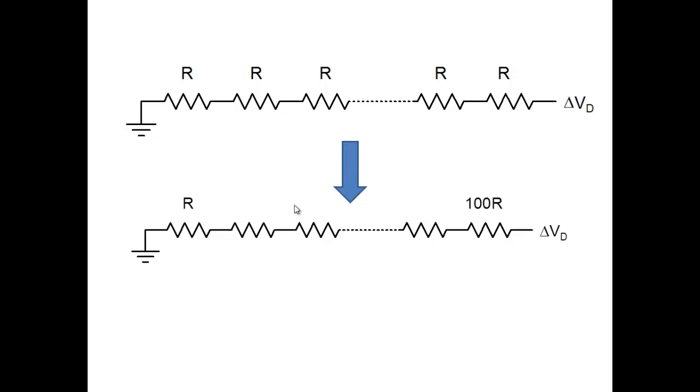At this end, remember, the resistance is still R, because near the source nothing changes. So this element is R. And at the pinch-off point I've arbitrarily put 100 R. You can put 1000 R depending on how large the resistance became. Correct? Because there is a very low electron density and the resistance of that particular element will be very high. Now do a 0.2 volt increment here. Increase the drain voltage by 0.2 volt. What would happen? Where will it drop?